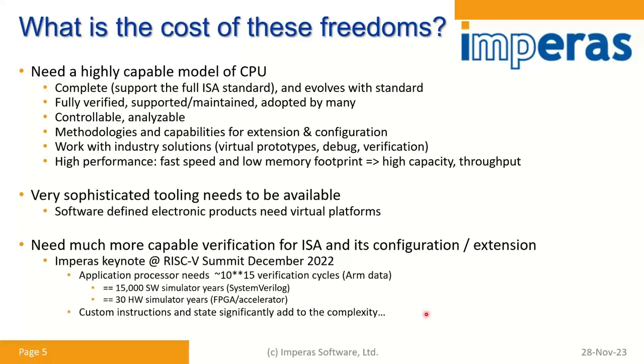And we dug up some information on the ARM process where they talk about 10 to the 15 instruction cycles that they have to validate for a high-end application. If you put that in context, it's 15,000 years of a simulator or 30 years of an emulator. And this is why people building high-end processors have tremendous verification environments with a lot of verification technology in it.